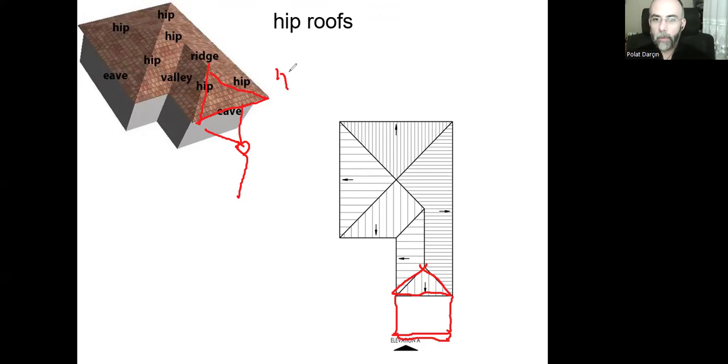Let's say this has 45% slope. Then this is what I need to do. That's my first point. I need to draw 100 units, find the second point, and go upwards for 45 units this time. Find the third point and connect the first and the third one, and transfer the ridge point. This hip, and then it goes like that, and we have the eave. So it's completed.